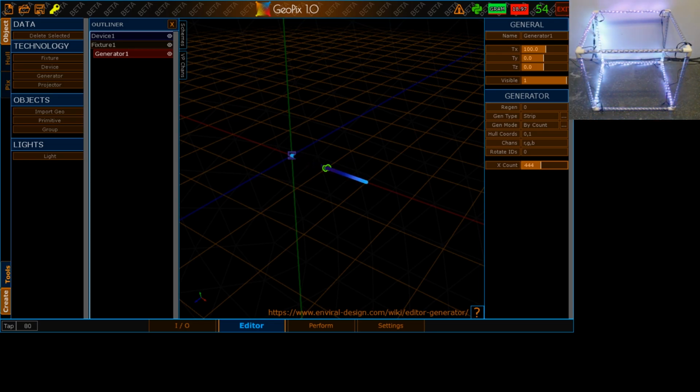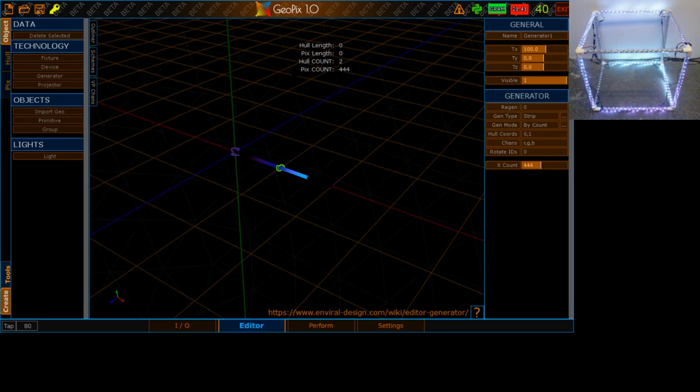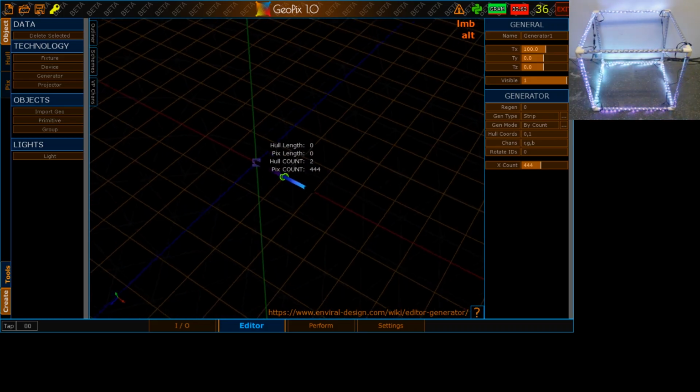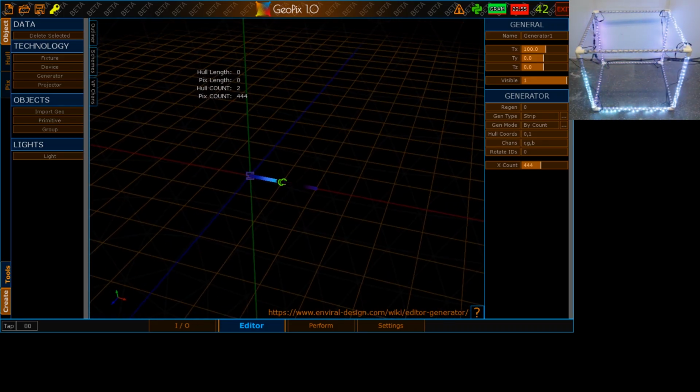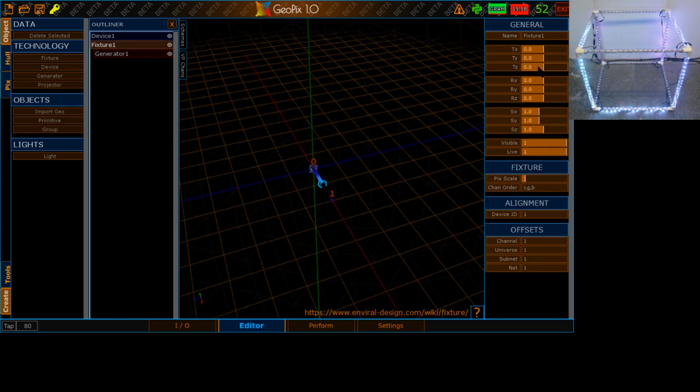If I change that now, you can see we're actually lighting up an entire LED cube, with the exception of the very last pipe, which I haven't actually connected. So that's cool, but there's no mapping. It's just a very straight horizontal trace from the first LED to the last LED, the 444, in a sequential pattern. The real cube shows that the LEDs are wired in series in a continuous loop, but there are actually 2 points where I jump in order to create a single data path for all of our LEDs.